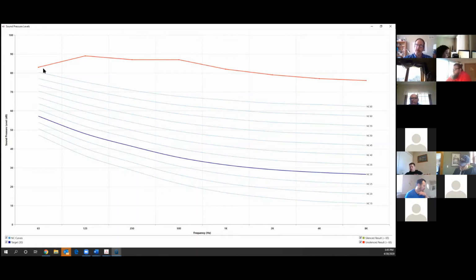It's also important to note that the octave band levels at different NCs are different. So it's harder to come by losses at 63 hertz. You don't have to go as far to attenuate 63 hertz, for example. And 63 hertz would be like the rumble of a fan, the really low sound that you get off of a fan.